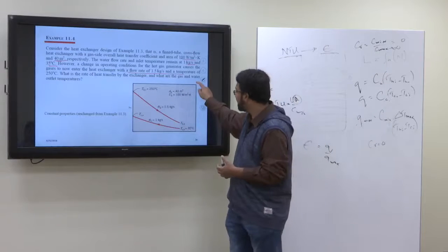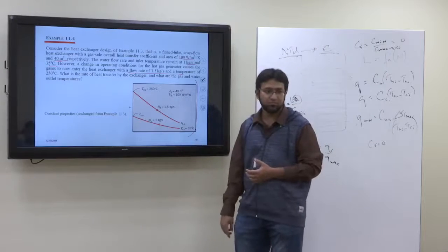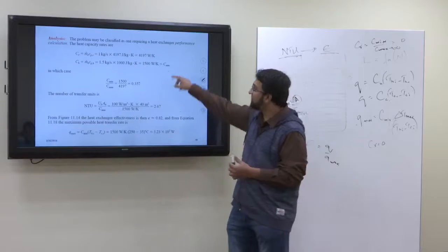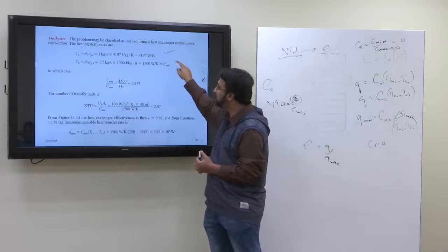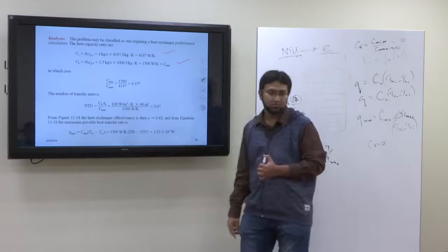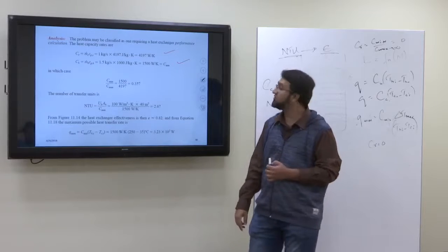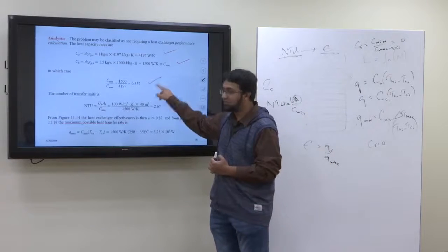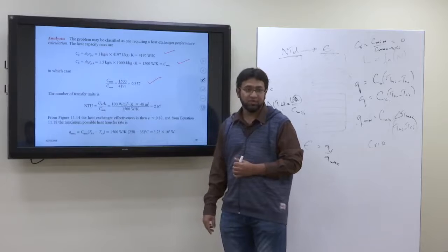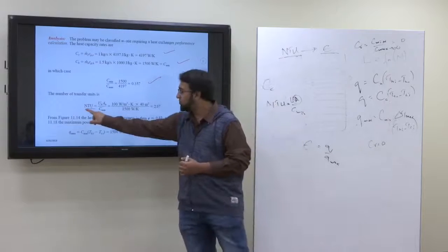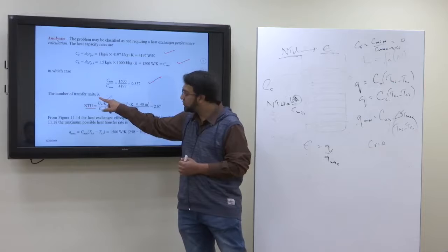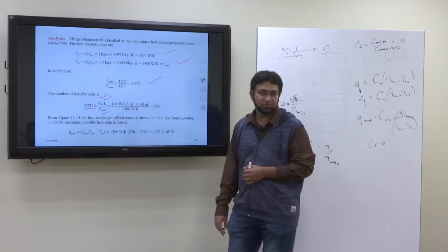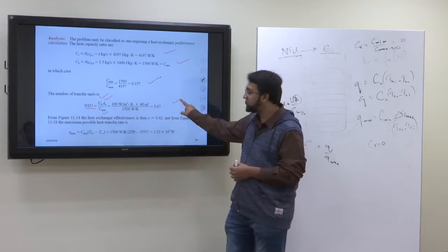Again, you will first draw this thing. You will first have to find out CC and CH. After that, you will find out what is CR. Then you can find out NTU because you know the area, you know U, you know C minimum, you know all these things. So you'll find out what is NTU.